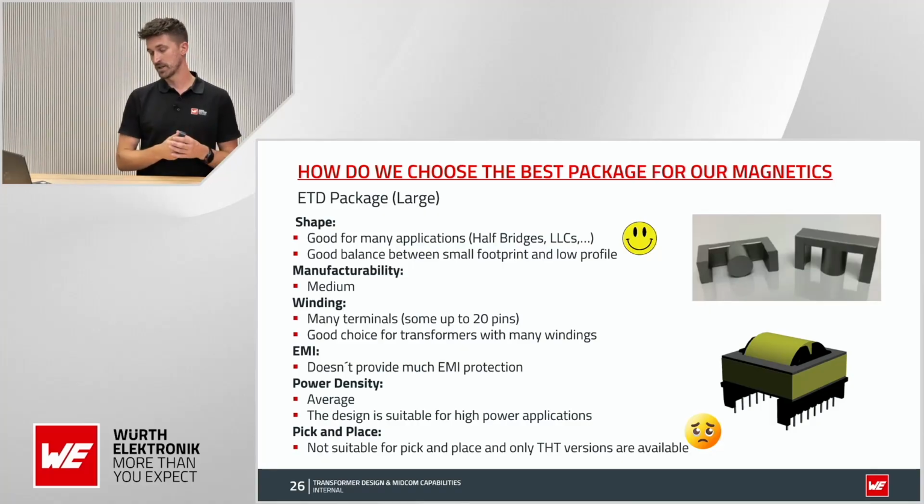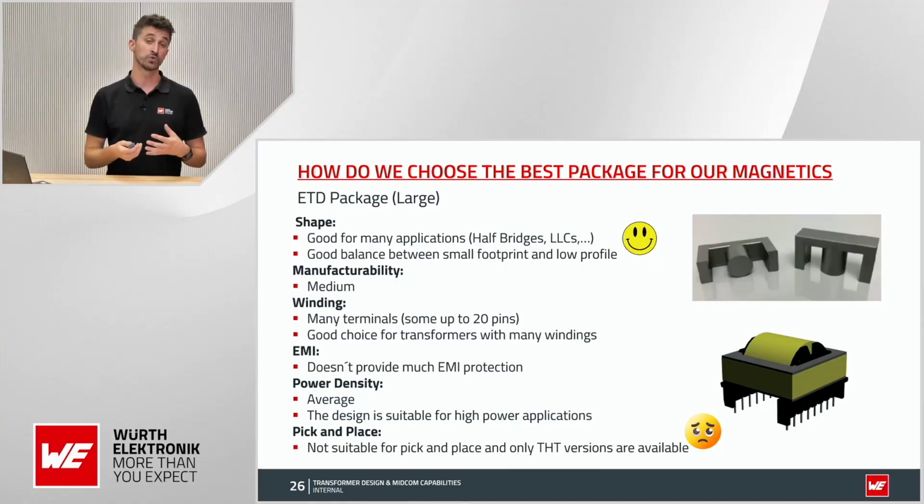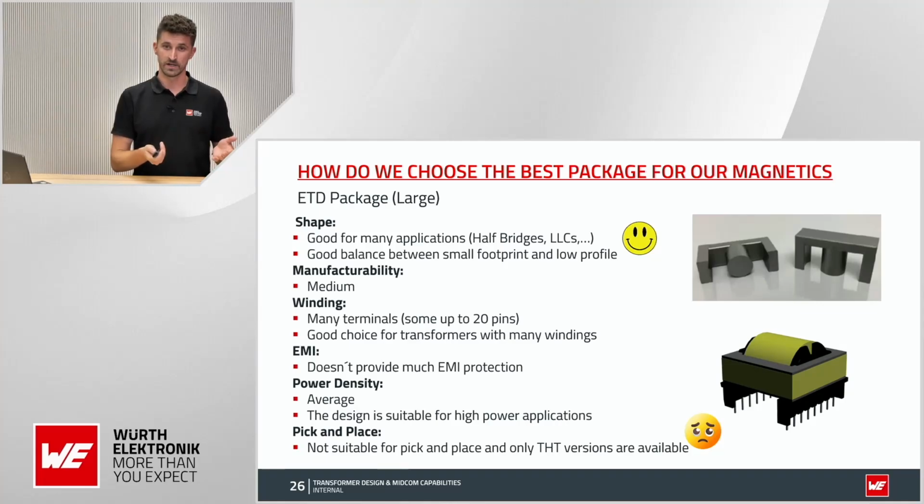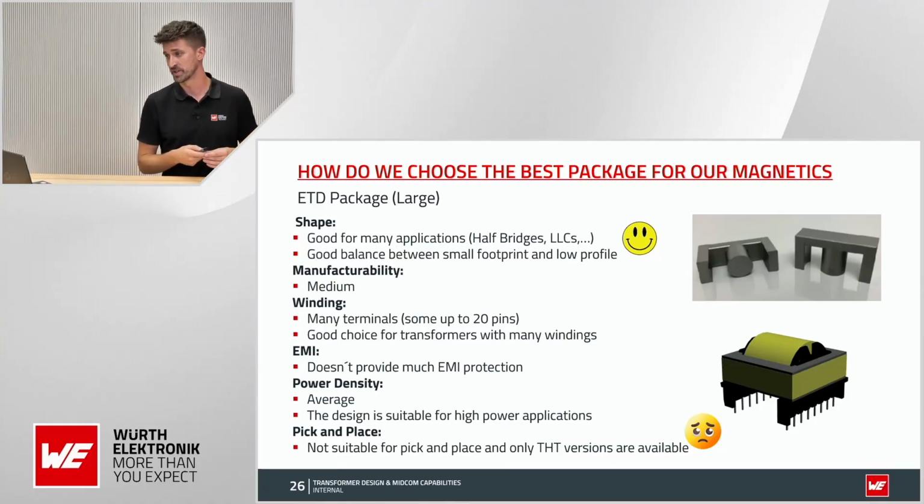And now finally, I present here one of the biggest packages we have in our portfolio, which is the ETD. This package, thanks to its size and number of pins, is good for many applications, such as half bridges, LLCs, push-pull, you name it. Unfortunately, due to its big size, it's only available in through-hole. Therefore, pick and place is not available with this one.